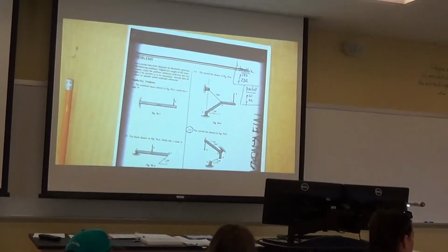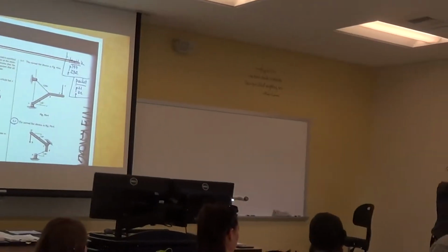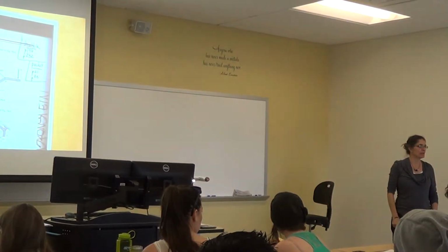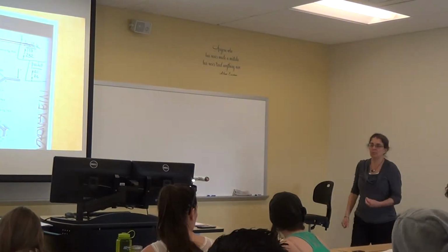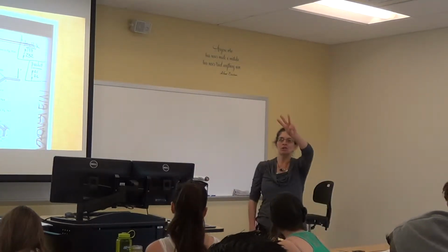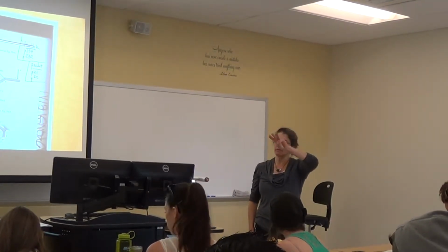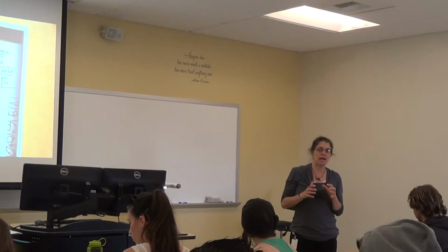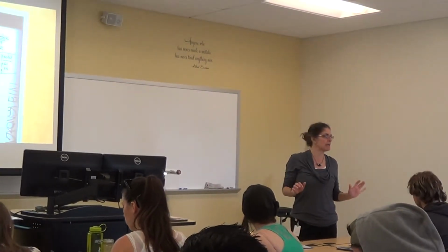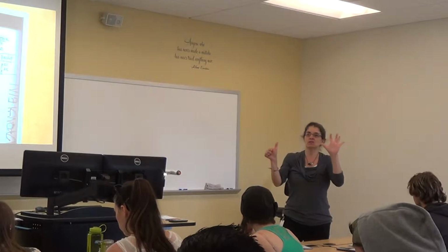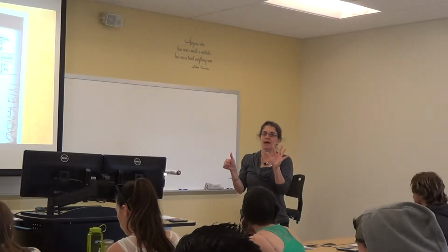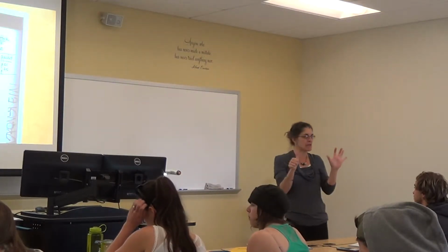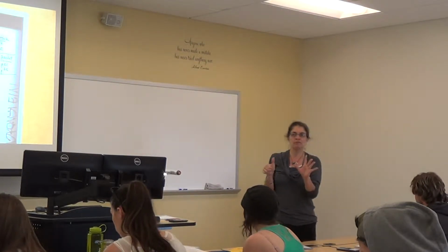Can I spin? So it can be forces. Right, in X, Y, and Z. In all three. So the reactions at a support of a ball and socket joint are three: force in the X, force in the Y, force in the Z, right? But a 3D connection has the possibility of resisting how many? All six. 3 forces and 3 moments, right? Everybody has that? On a 3D connection, there's a possibility of it resisting 6, having 6 reactions at a support. 3 forces, 3 moments.